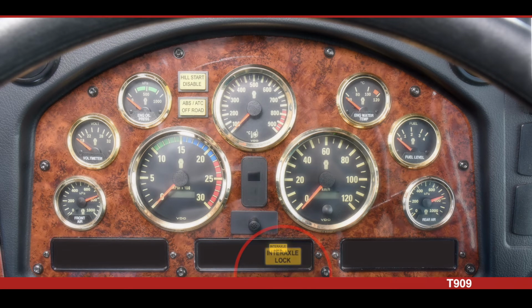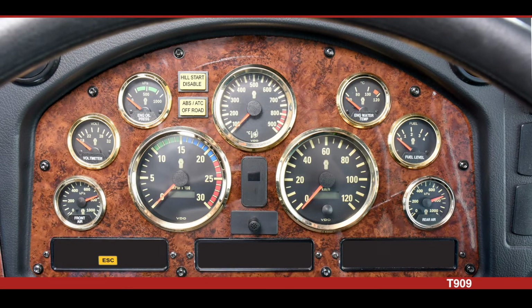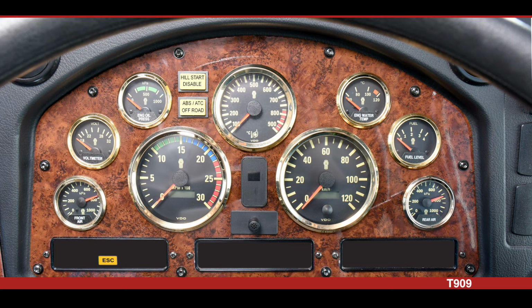The interaxle lock will illuminate when the interaxle or power divider is activated. The ESC light will illuminate briefly and then go out when the ignition is first turned on. The ESC or traction control warning lamp will illuminate whenever the automatic traction control, ATC, system detects drive wheel spin. The lamp will remain illuminated as long as wheel spin is detected and the ATC system is applying the drive brakes or reducing engine torque.